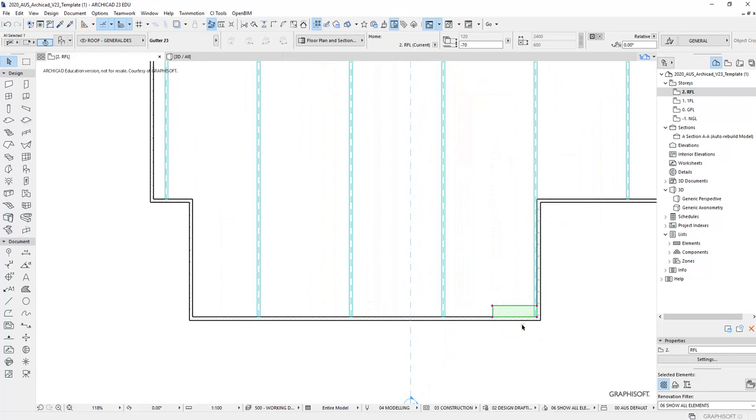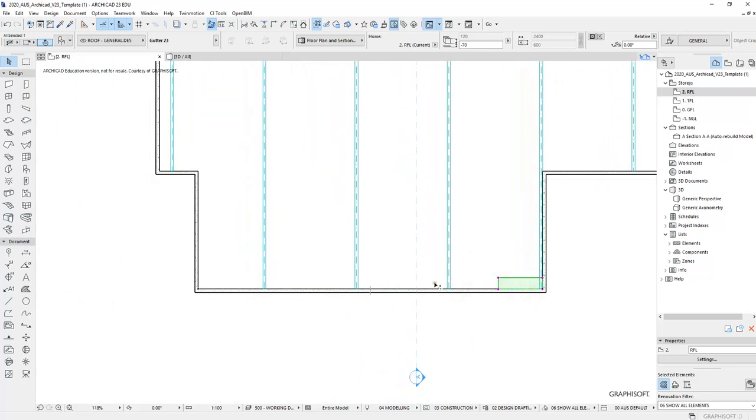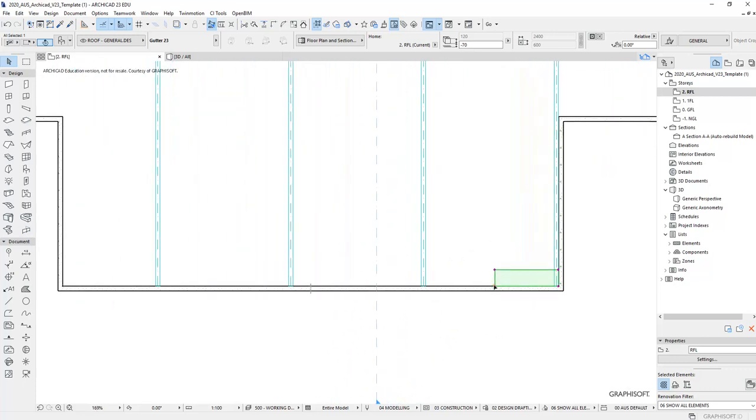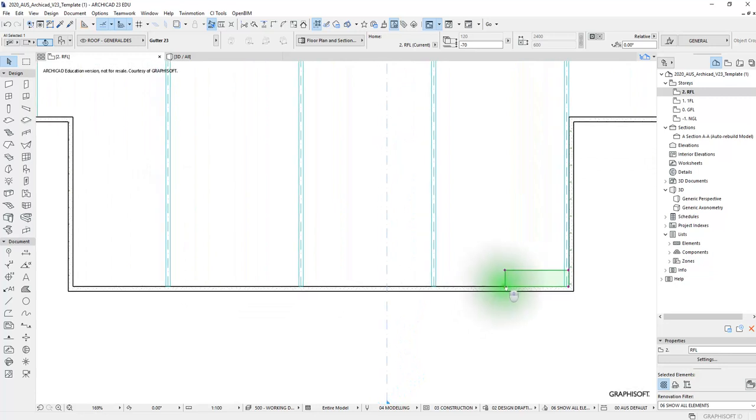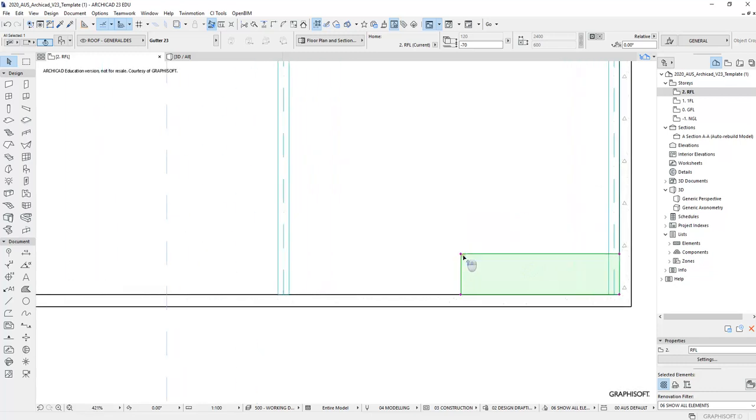Now one thing I would like to show you is this. If you were to stretch the box gutter, yes, you will go and click on this node, right? Now let me share this with you. These two nodes will give you two different ways of stretching and adjusting the corners.